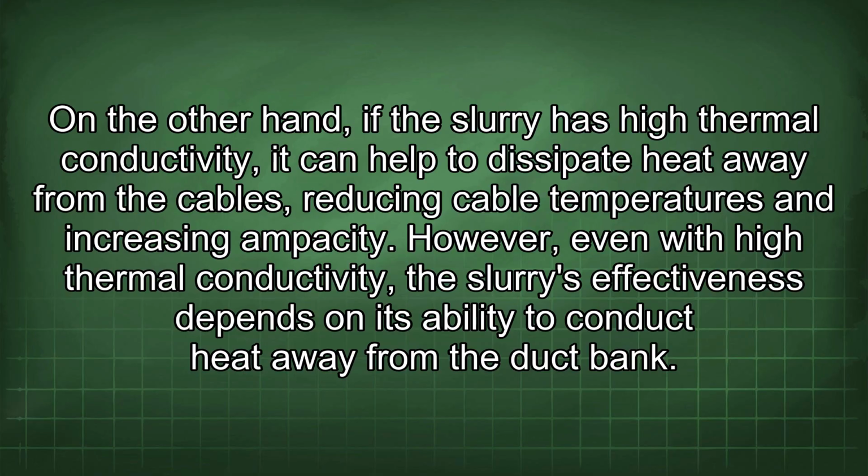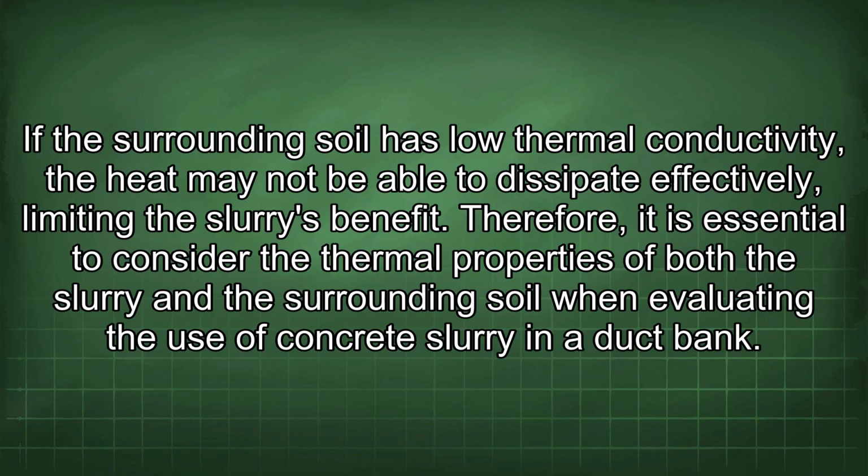However, even with high thermal conductivity, the slurry's effectiveness depends on its ability to conduct heat away from the duct bank. If the surrounding soil has low thermal conductivity, the heat may not be able to dissipate effectively, limiting the slurry's benefit. Therefore, it is essential to consider the thermal properties of both the slurry and the surrounding soil when evaluating the use of concrete slurry in a duct bank.